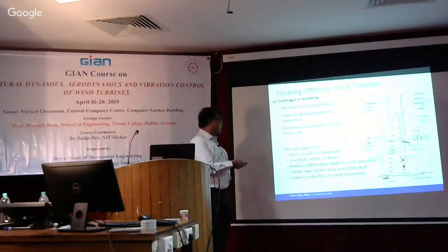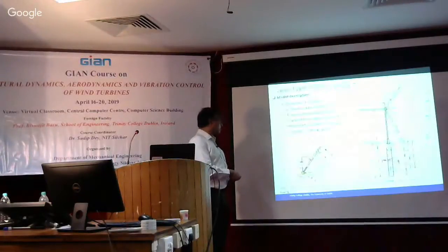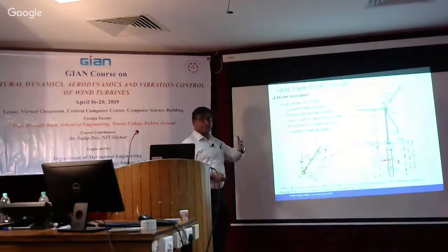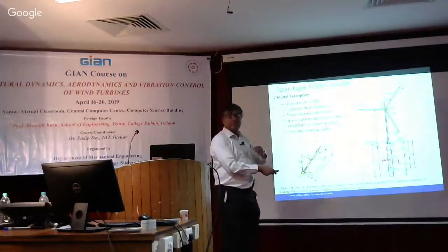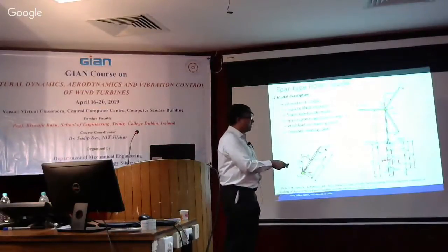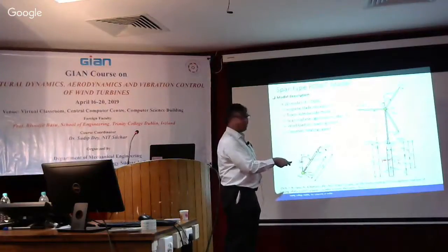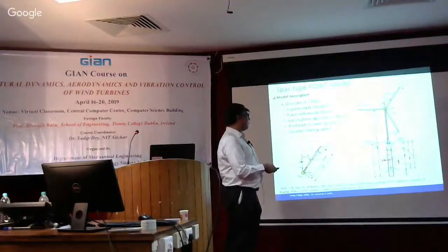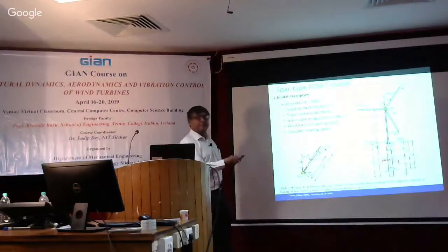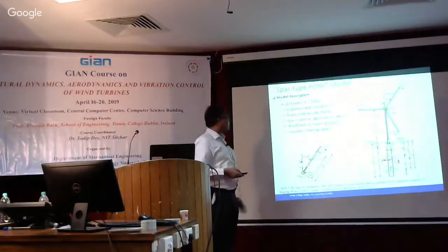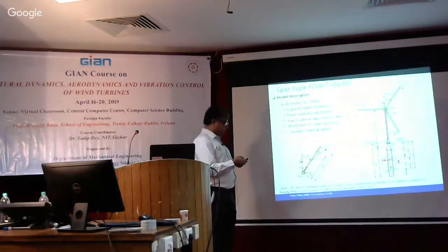But something can be done, and based on that, what we can do is obviously write the equations of motion, just now as I said, and this is the schematic diagram with the degrees of freedom. So this answers your question actually, in terms of how we deal with this. You can see there's a lateral spring stiffness, a rotational stiffness, and a vertical spring stiffness. The details of this are available in this paper. And the expressions for these springs are also derived based on, as I said, the interaction of the fluid with the structure. So this is a 7-degree of freedom system, a 2D model,